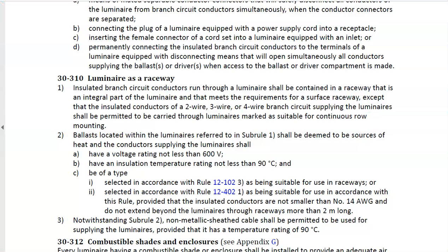Induction lights, or discharge lighting as we refer to it, is going to be different because we have transformers, we have inrushes, and we have collapsing fields around those ballasts. Those ballasts are transformers that happen inside of it. So let's go through some Canadian Electrical Code as it pertains to Section 30 over here.